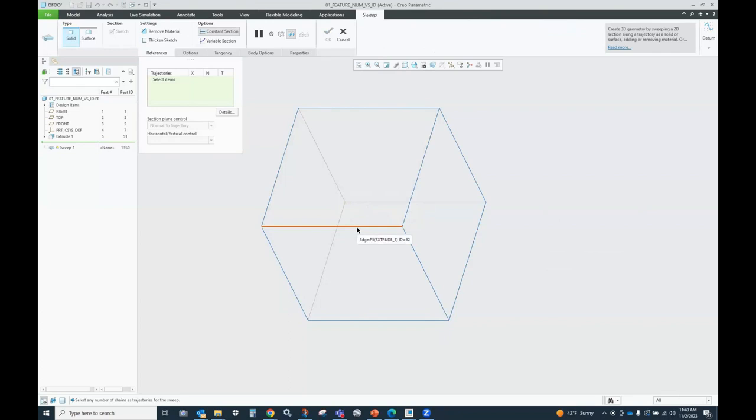Now, with a sweep, I don't have much in that list other than the edge. Well, I guess in this case there is an intent. Sometimes you'll find that there's no intent selection there for the sweep, and you have to use your shift key to get there, right? So, an example might be, what if I use that edge, and if I use my shift key, what do I get here? I get that. Now, that is not a default intent selection. That certainly is one that I have to kind of force using my shift key, right?